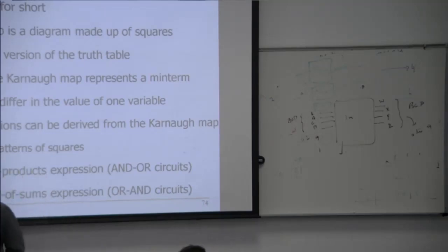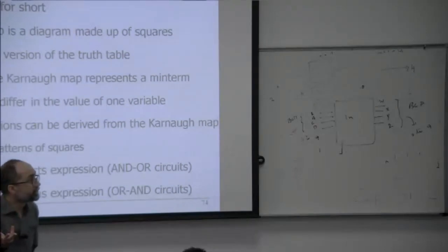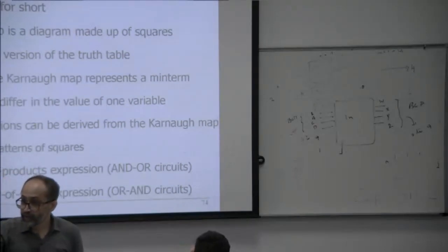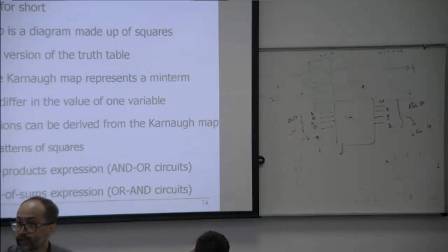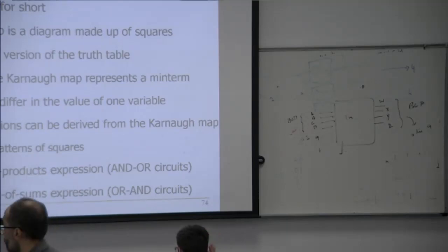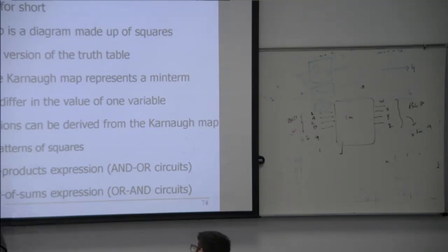We have different implementations. We can have the SOP implementation, the POS implementation, the NAND implementation, and the NOR implementation. Using the Karnaugh map, we can extract the SOP implementation and the POS implementation. If you have two different functions, the Karnaugh map is not that efficient. But if you have multiple circuits, we can also use the logic sharing approach. This approach is called what? Logic sharing of the gates. Any question?